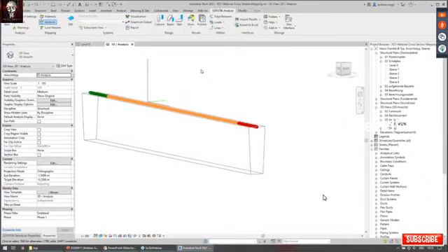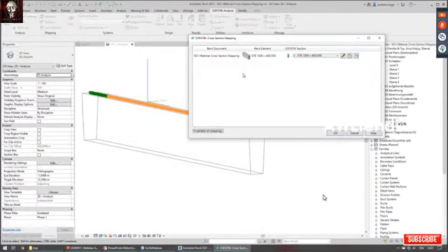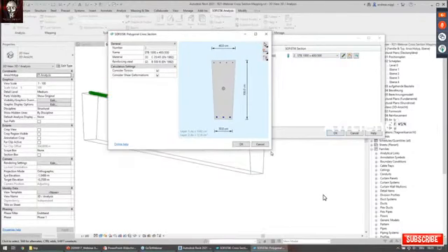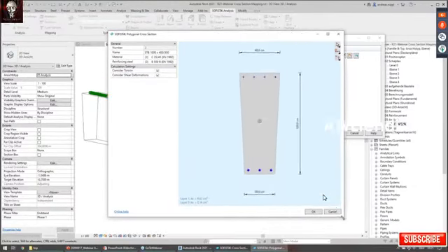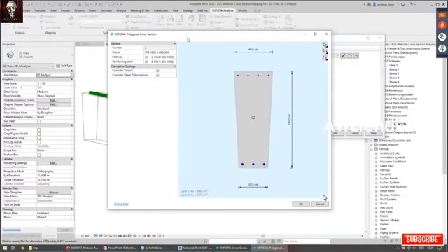So in this case, as said, this is a trapezoidal beam, a custom family, which you created by yourself. And now when clicking on the sections mapping command, you see that we now didn't assign any standard section. It could be possible, of course, so you could also assign the standard section here. But in this case, we created a so-called polygonal or free sectional layout. So it's not a standard section anymore.